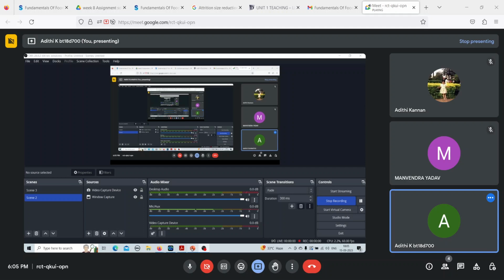Okay, hope this is clear. For Kick's law, m is equal to 1. For Rittinger's law, m is equal to 2. And for Bond's law, m is equal to 3 by 2. So you can just substitute m in this equation, integrate it, and get the formula for each of these laws.